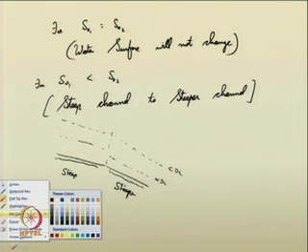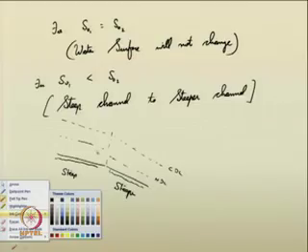If the water surface goes below into zone 3, the water surface slope has to be always positive in zone 3. So, if it goes below here, that will not be possible. Similarly, here you cannot raise the water level in this situation.